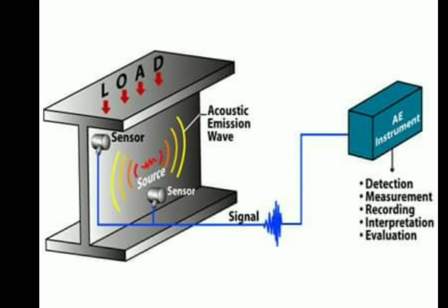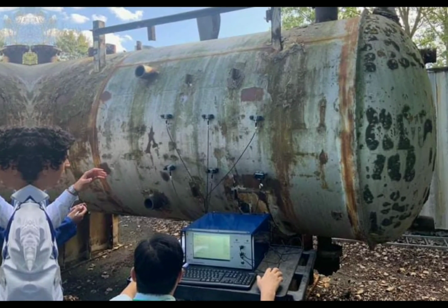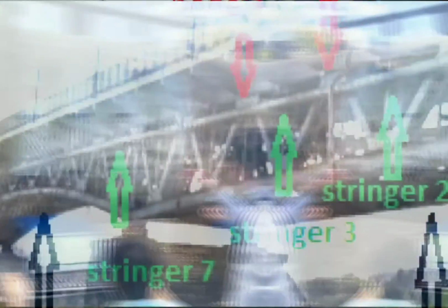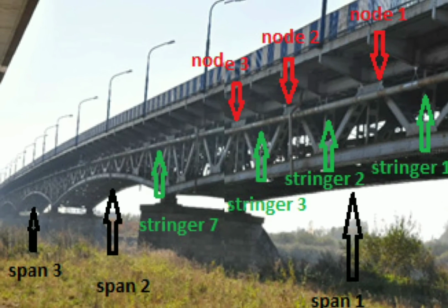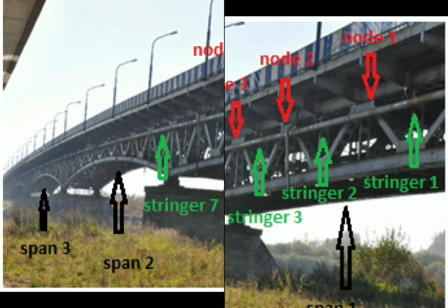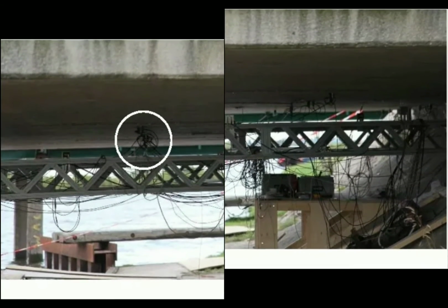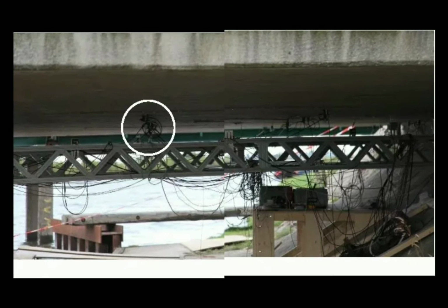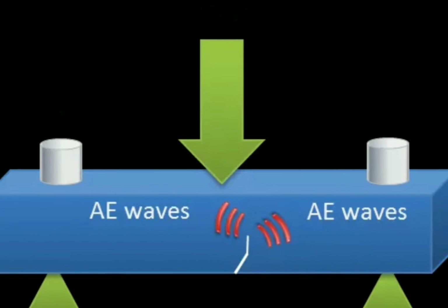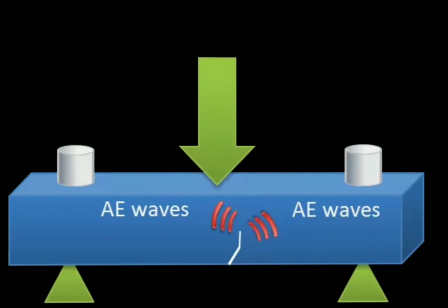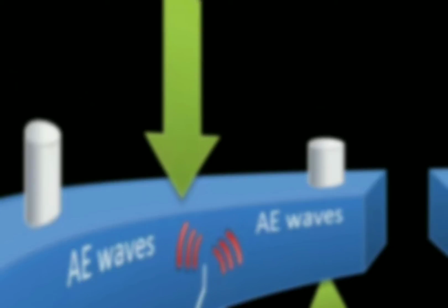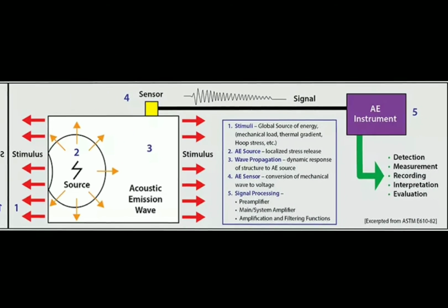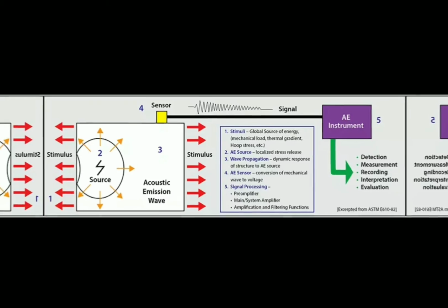Some of the advantages of the AE technique over other non-destructive techniques are its high sensitivity, source localization capability, and ability to provide monitoring in real time, that is, damage detection as it occurs. Study of AE started in the 1950s, and AE techniques found initial application in monitoring pressure vessels and aerospace structures. AE was first applied for bridge monitoring in the early 1970s, but the use and study of AE for monitoring bridge structures rose with a rapid increase in computing resources and development of sensor technology.